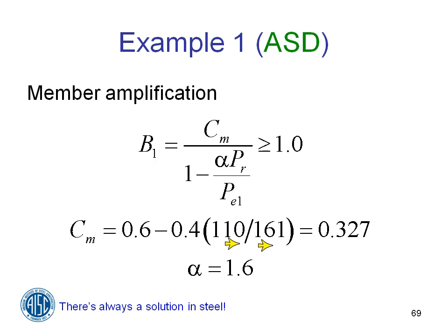Okay, and one more question. Do we use the reduced stiffnesses for drift calculations or just for stability consideration? Just for stability considerations. If you're talking about drift, I'm going to limit the drift of my building, no, you don't use the reduced stiffness. The only time you use the reduced stiffness is for stability calculations. Okay, if you're talking about deflection of a beam, right? You may have a beam in your structure that's part of your moment frame, and you're worried about the deflection on that beam. You don't use the reduced stiffness for calculating that deflection.